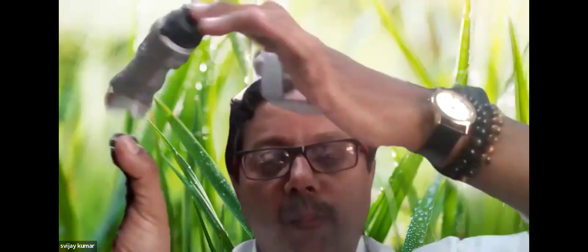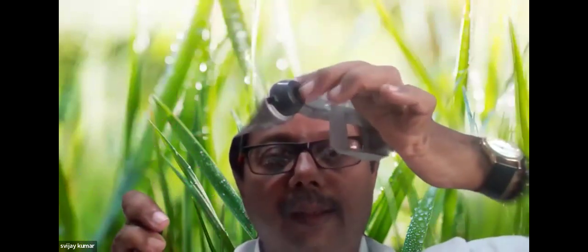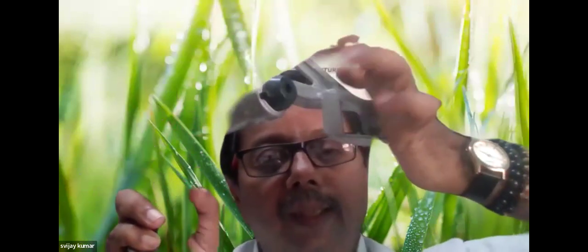The nozzles are all openable. Every nozzle can be opened with the help of a spanner and it can be cleaned and put back. So maintenance is actually very minimum. And if the water source is like a river or a tank, around the foot valve you put in a wire basket so that big chunks of algae or other moss will not enter. And then the water is pumped into the system.